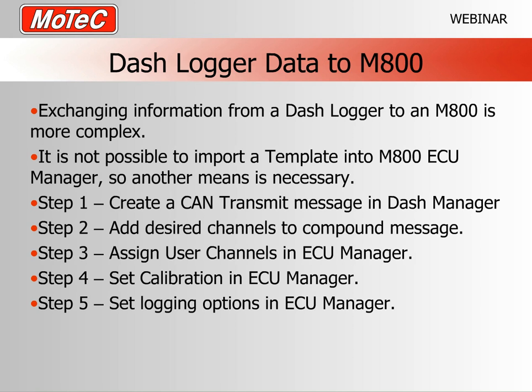Once again, there are 5 steps in this process. We'll go through each of these in turn. Firstly, we need to create a CAN transmit message in the Dash Manager program. We add the required channels to this message.